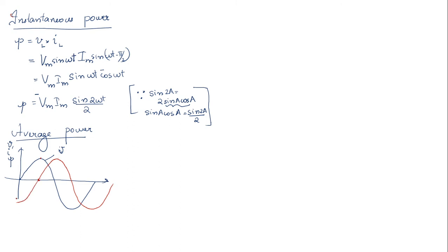As we have already done in the previous case, what I'm going to do is to find the average power. First, I'm going to mark all the intersecting points with a dark color, and I'm going to split it into different intervals. For this purpose, I'm going to take the green color and make intervals like this. And we will check what is the value of voltage and current in each of these intervals. See here, the red color shows the current waveform. Next, we are going to draw the power waveform. So let's check the first interval. Before that, let's mark these values.